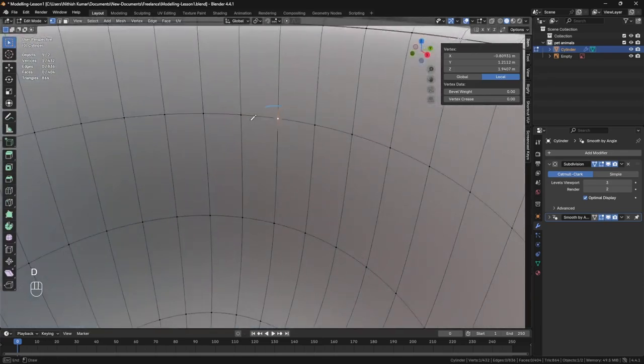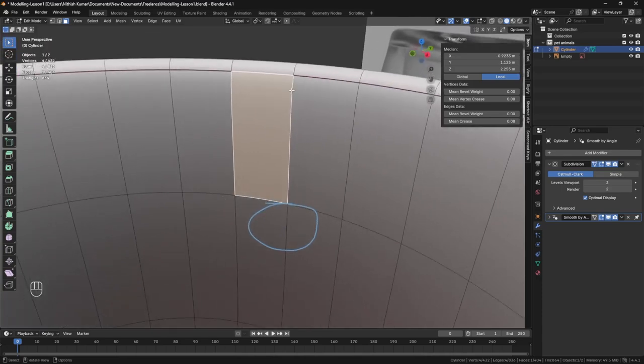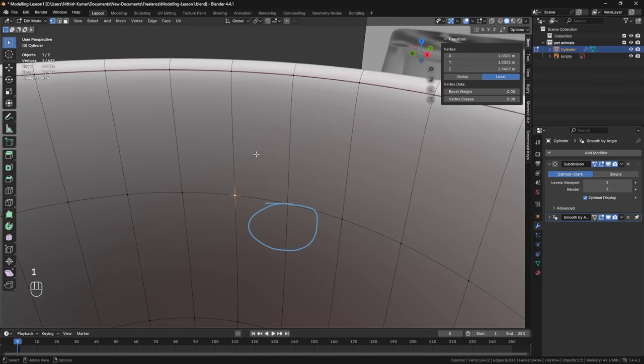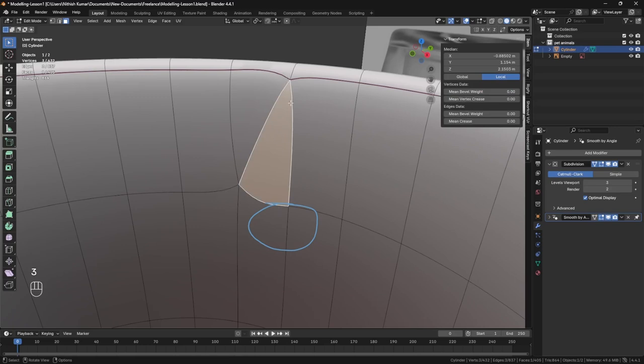This one is called a vertex, and I've selected only one vertex out of 432. And if I press the face, these four vertices combined are called a face. A triangle is something I'll show you. You can just press J. So this one is a triangle. Three vertices make a triangle.